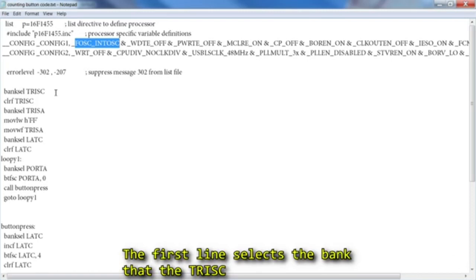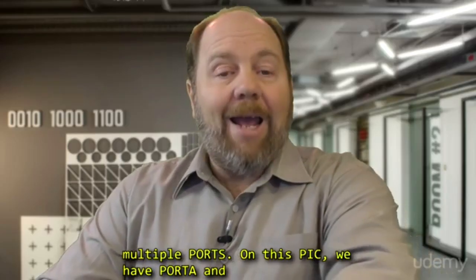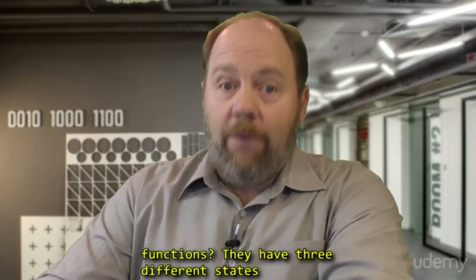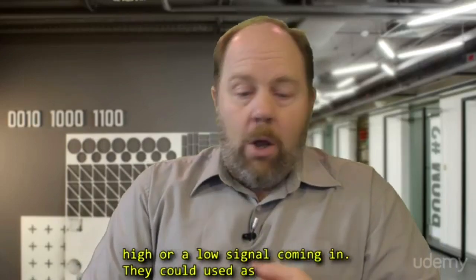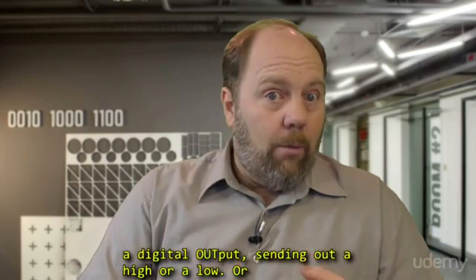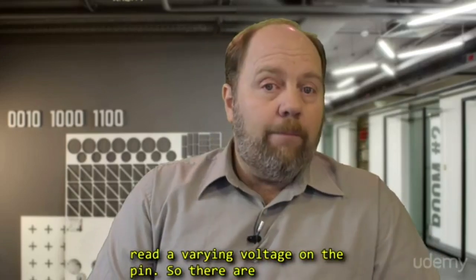The first line sets the bank that the tri-state C register is in. On the PICs, there are usually multiple ports. On this PIC, we have a port A and a port C. And you remember many of these pins had multiple functions. They have 3 different states, basically. They can be a digital input, reading a high or low signal coming in. They could be used as a digital output, sending out a high or a low. Or some pins could be set up as an analog input to read a varying voltage on the pin.